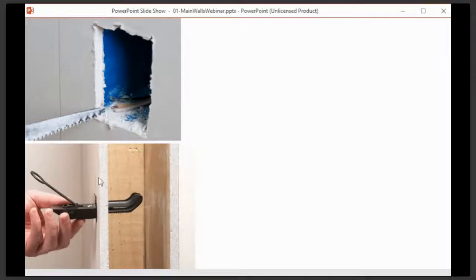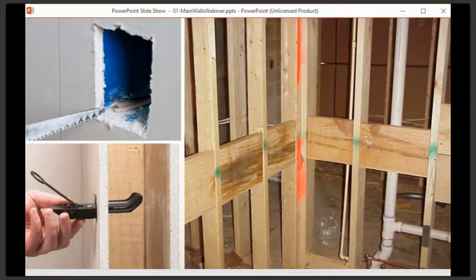Now, if you look at this cross section of a stud wall, you can see with this hollow, if you put anything of weight on here, the plaster is not really going to be strong enough. There are special fixings you can get for plasterboard walls, special screws that are supposed to hold heavy weights. But you know what? They won't hold really heavy weights. They will only do so much. And this is exactly why I was showing you this earlier on. If you are going to use this type of wall, which you probably will quite a lot, you do need to make sure that if you want to put in heavy items, you provide some type of blocking work or blocking diagram, so that the walls can be strengthened to support heavy pictures, heavy mirrors, cabinets, etc.